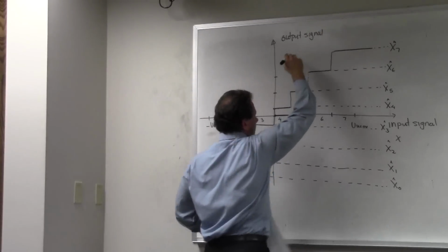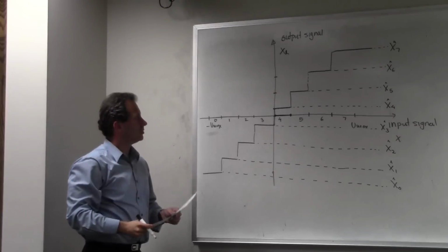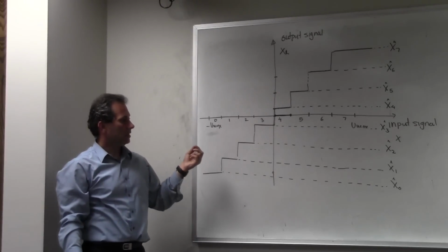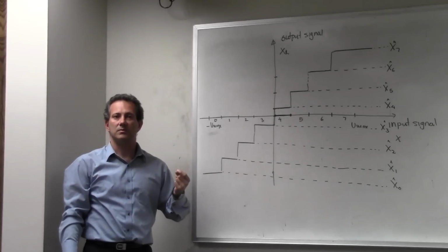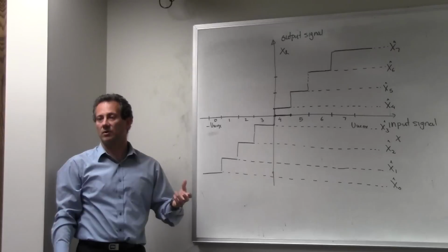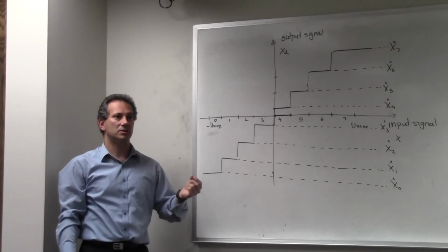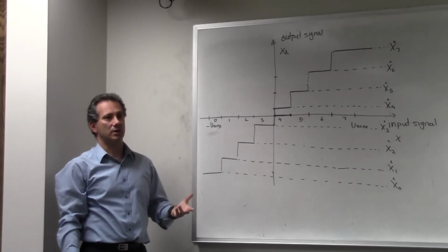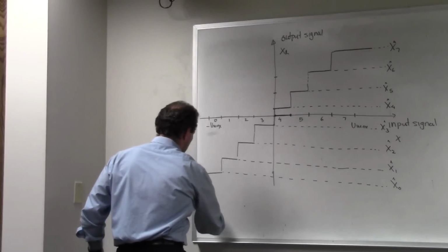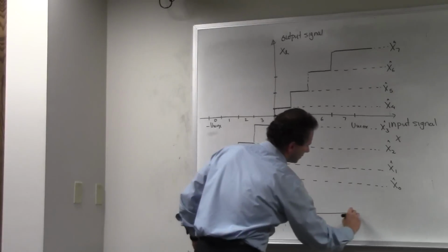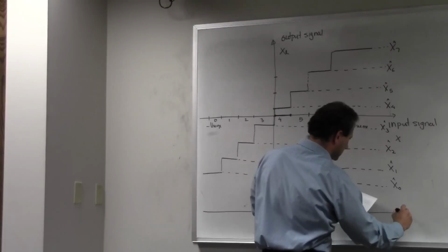And obviously the point of greatest interest to us is this. When we perform quantization, we're representing the signal value with something that is not the exact signal value. We're making some error. The point of greatest interest to us is how large is this error and how do we control this error? Is this something that is within our control? To illustrate what is happening here, let me draw this error as a function of the input signal. So this is your quantization error.